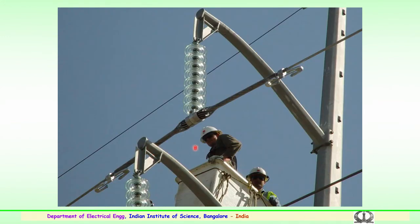So, this is a typical arrangement with the armor type of conductors which are seen here. This will act as a damping arrangement. Further, you can see the damper here which is connected at both ends of the conductor in case of aeolian vibration, galloping or wake induced oscillations. In case the tower or the conductor sees these, this will try to reduce the oscillations or damp the vibrations which are produced at low frequencies, and sees that further fatigue to the spacer conductor and also to the insulator string is protected.